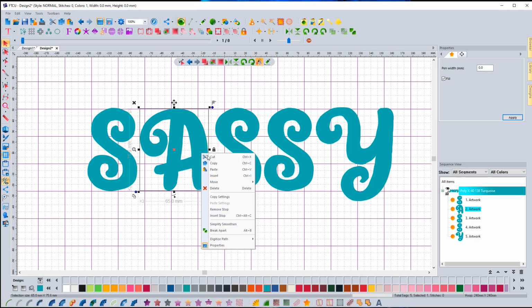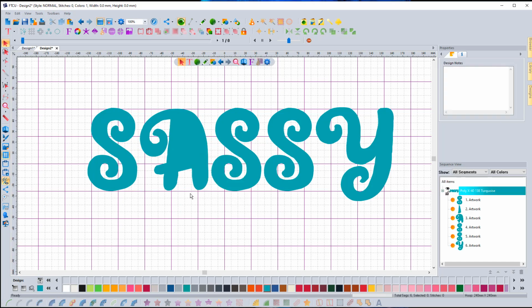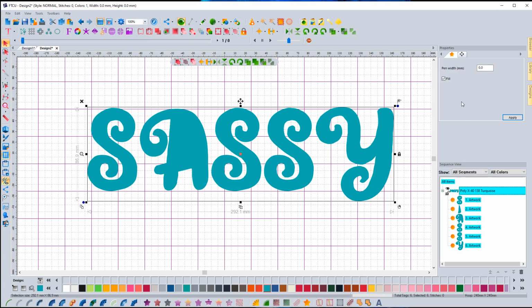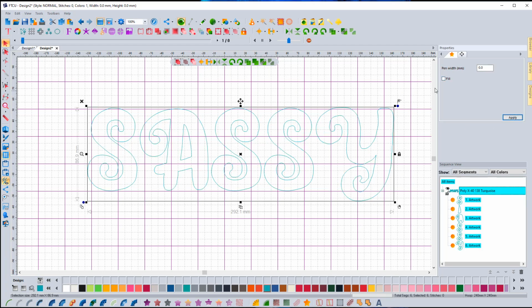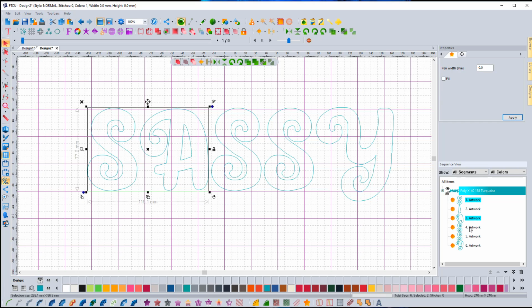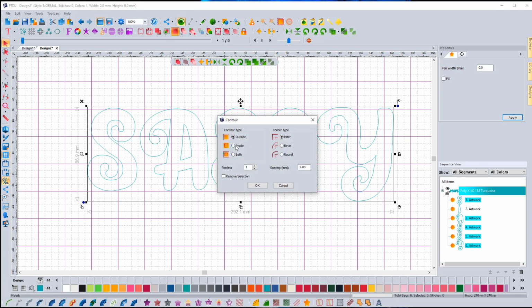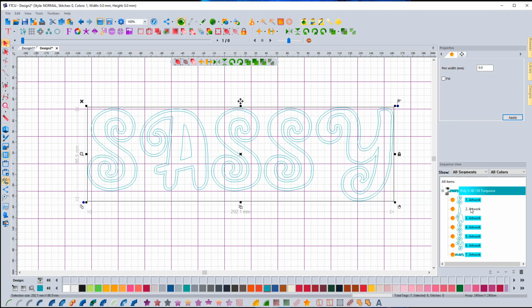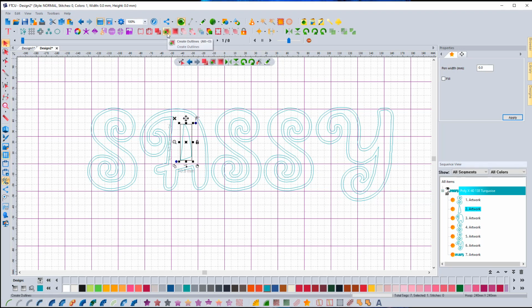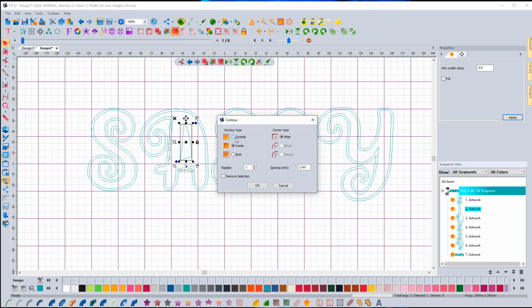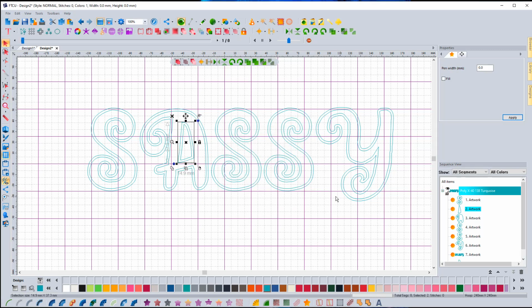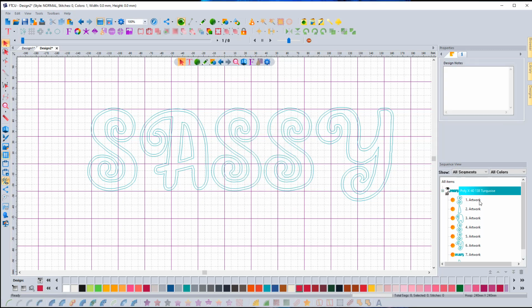Same thing, we're going to break this out of our A. Oh, this was why we wanted to have that be lines. And then we're going to take the guys that aren't part of a hole and do a contour on the inside, 2 millimeters, say okay. And then this one, we're going to do a contour outside, okay.